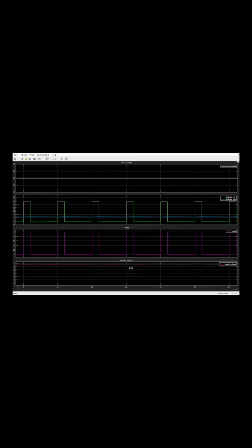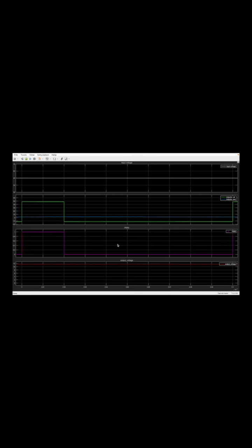And this output voltage will be reflecting in the output terminal of the buck converter. So basically we are giving a 60 volt input, and we are getting a 12 volt output. The magenta one that you are able to see is the pulse which we are having, and it is the time period which is shown between this. If we consider this part, then this is the total time period for which we are operating. So this is the TS part.